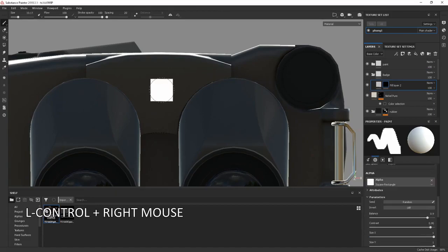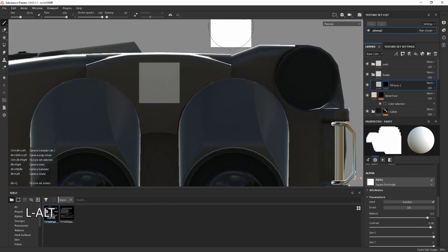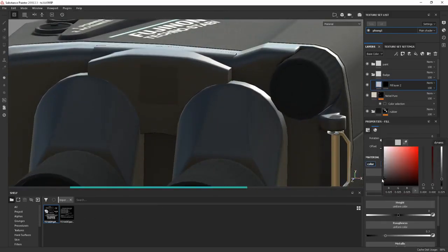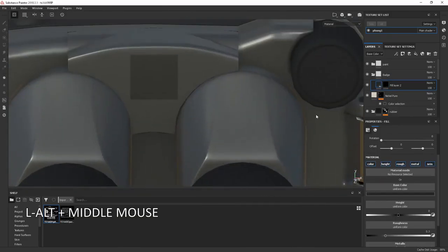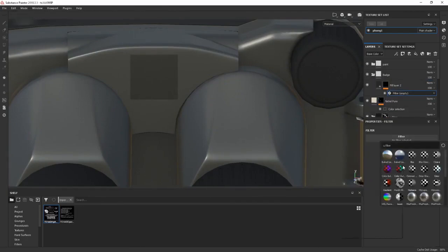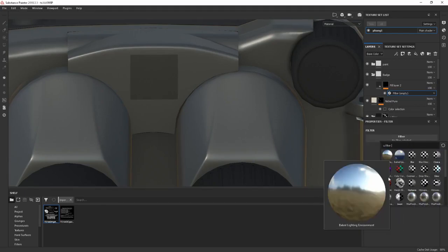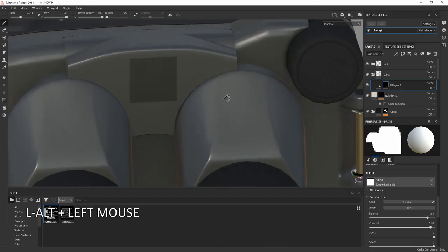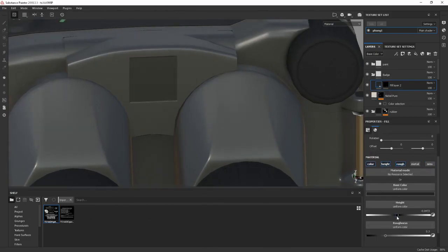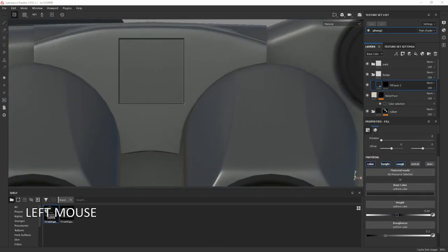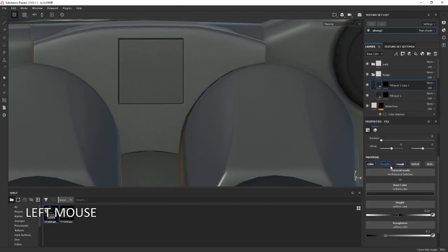I'm going to use a fill layer and a black mask and paint in where I want a square, and I'm just using the color difference to tell where it's going to be. It needs to be a slightly different gray. And I'm going to use that blur and layers trick that I did before to get some nice round edges to everything. Just play with the height a little bit so I can inset it. And then I duplicate that.